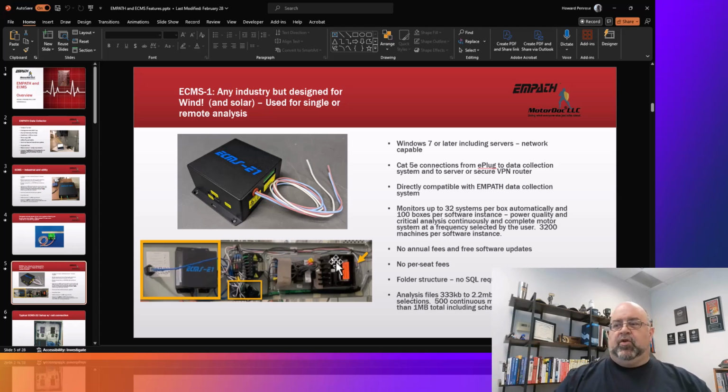So we ended up going in, pulling the fuse block here, wiring everything on the secondary of the fuse block, using the control transformer power, which put out 5 volts to power this and everything else, and basically had it installed in about 30 minutes or less, plus an output cable to connect up outside to gather data as well. So all of that was set up in a matter of no time at all, and monitoring incoming power, and it's been there for about 4 years.